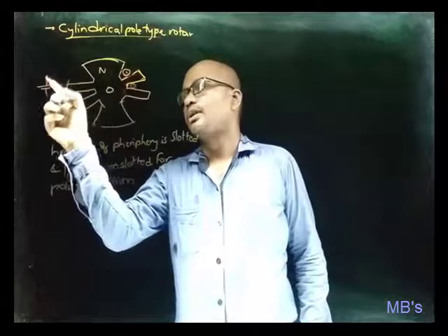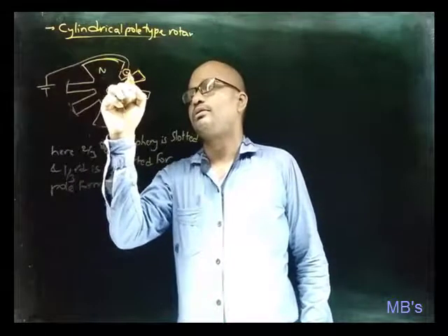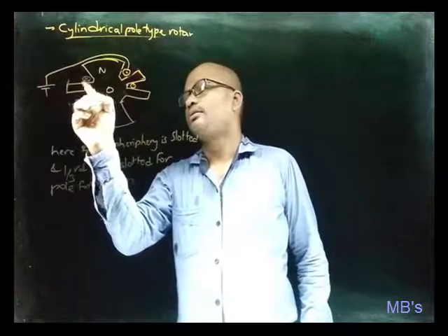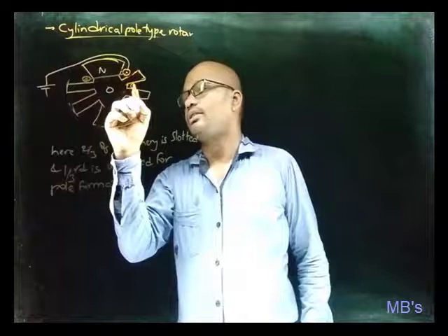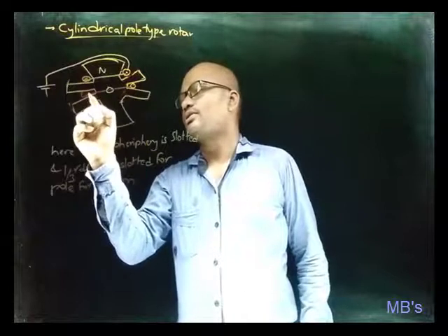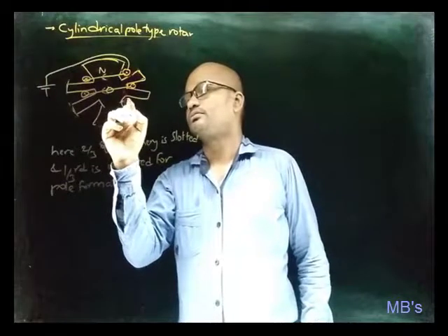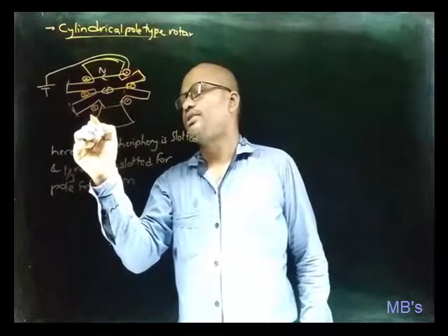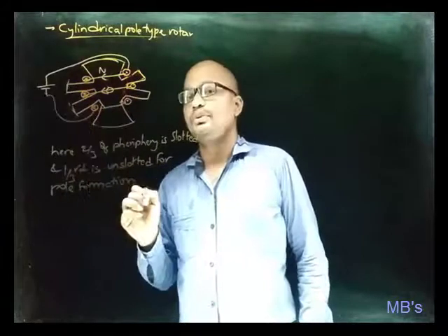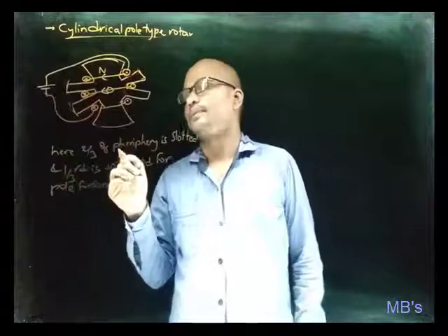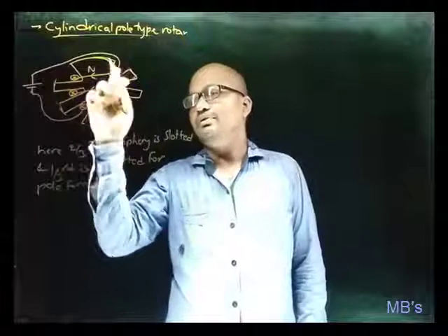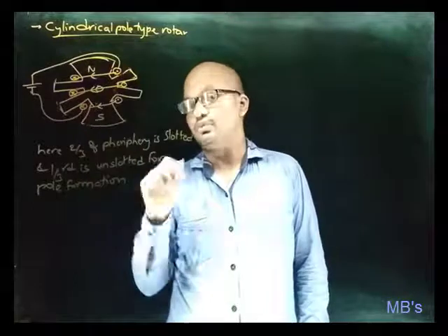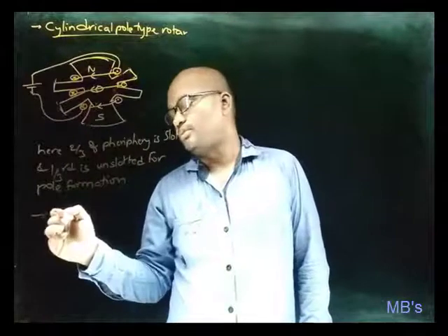Means current must be tending towards the outward side, and then like this, and then like this, and this is connected to the two terminals of the field excitation supply. By connecting the winding like this, you can make this portion act as north pole and this portion act as south pole.